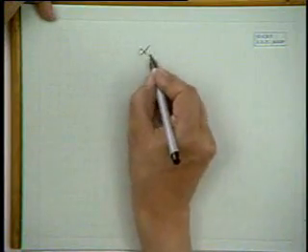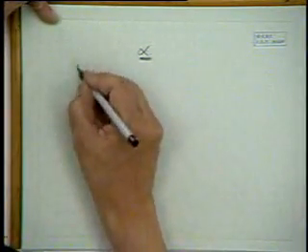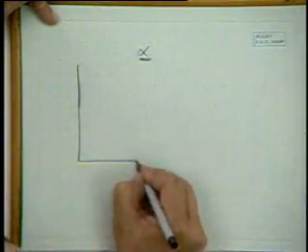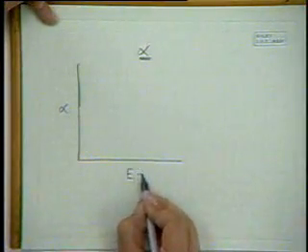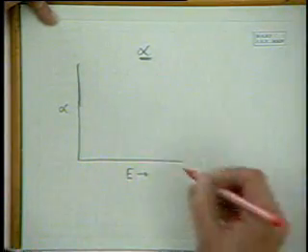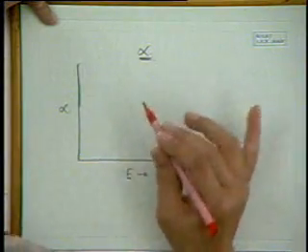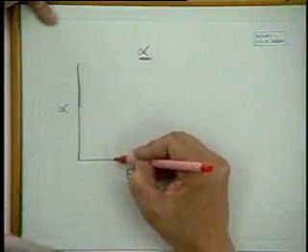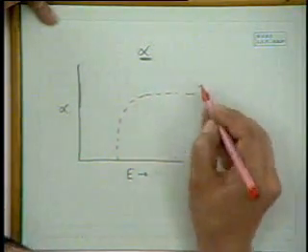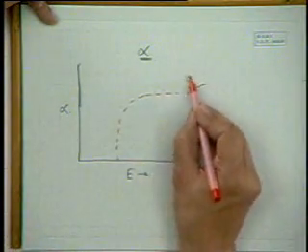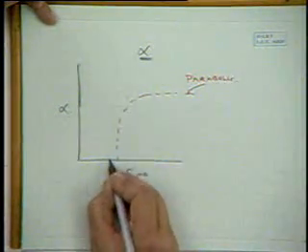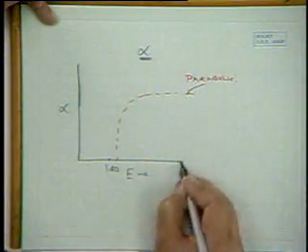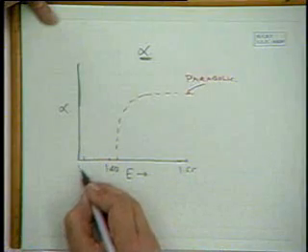even if you want to look at the optical absorption alpha, which is very easily measured, okay, optical absorption in gallium arsenide, you're not talking about ternaries or quaternaries. This is alpha against E. If we use the parabolic model without any band tailing, we get a variation of alpha just like that, very sharp, and the energy obviously is here something like 1.40, 1.55, 1.35, etc.